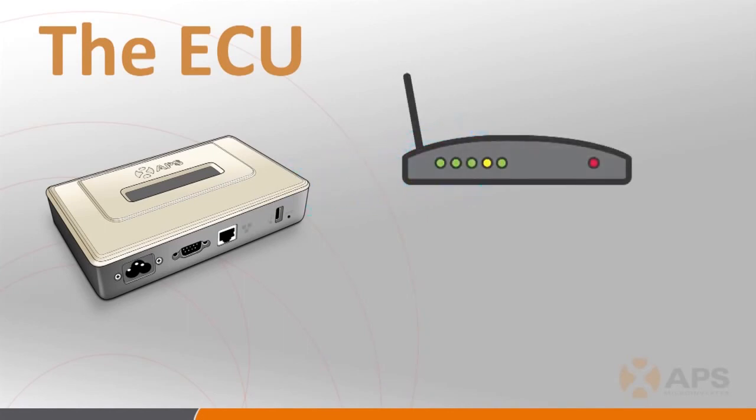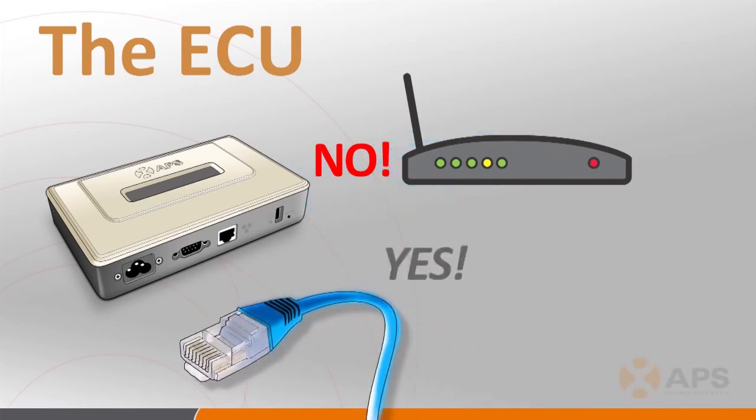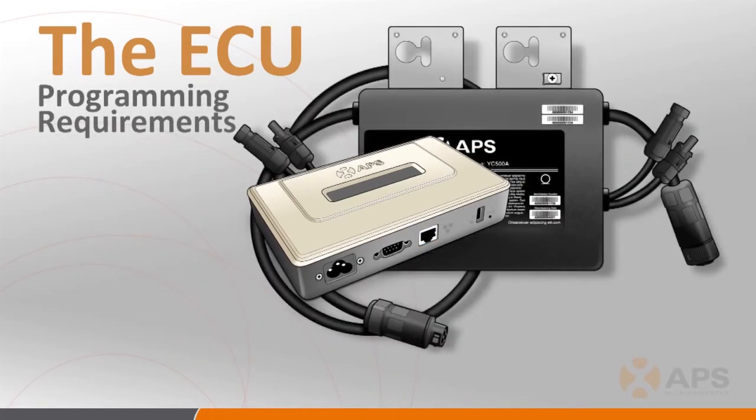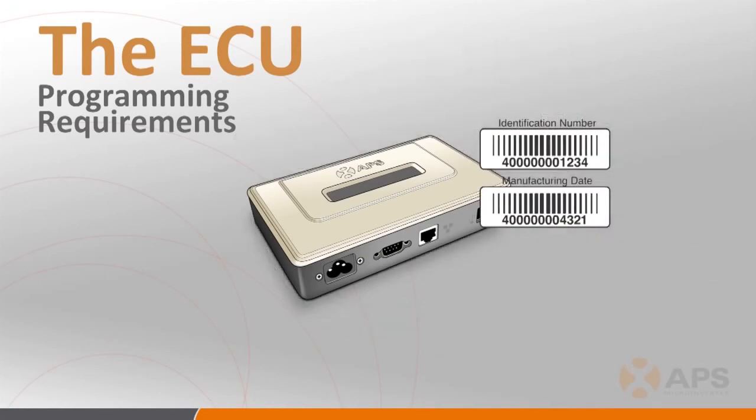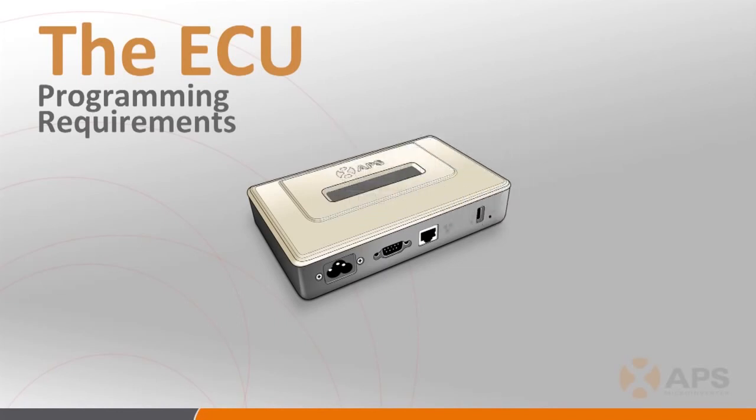It is also important to note that the ECU is not a wireless device and requires an electronic bridge or direct Cat5 connection to communicate to a network router. Before jumping into the actual installation of the ECU, it's extremely important to understand that it must be manually pre-programmed with the inverter UIDs prior to installation.